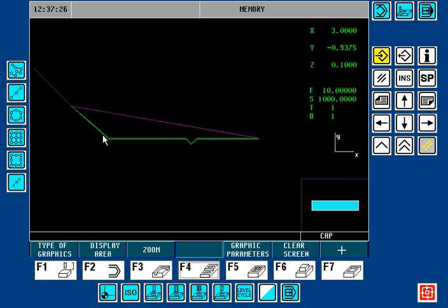So here, reducing our tool size down to only 1/8 inch diameter provided a solution for us, because the tool was now allowed to go down into this feature, this step, and it was allowed to tangent physically to this surface and this surface. So basically it was allowed to touch every line in the path.